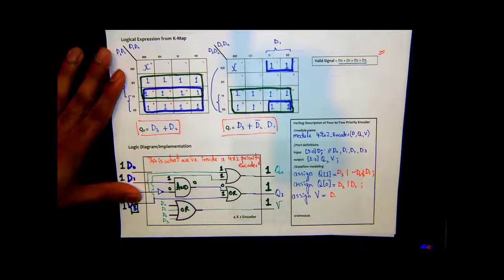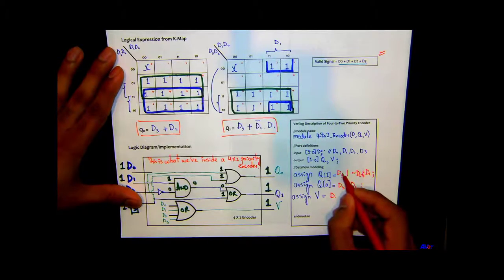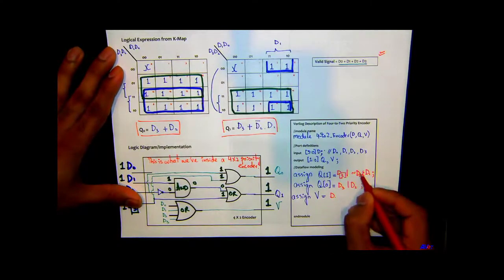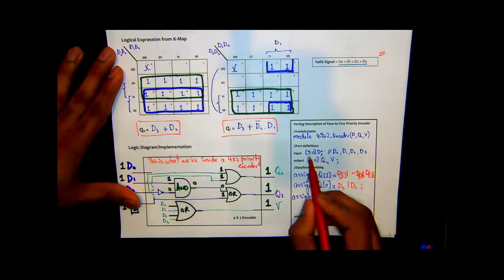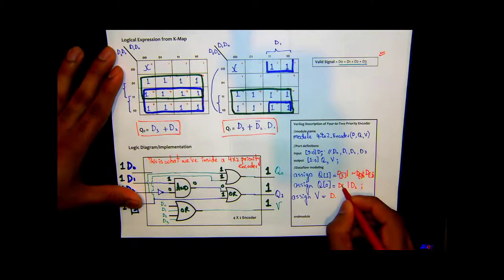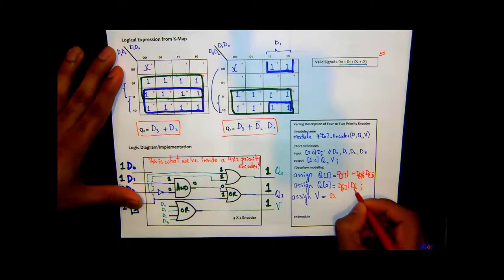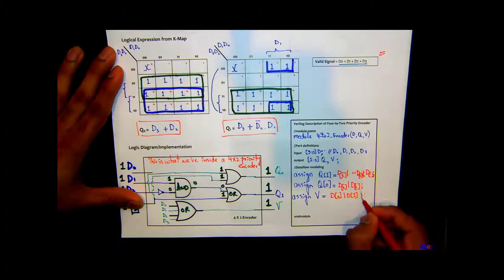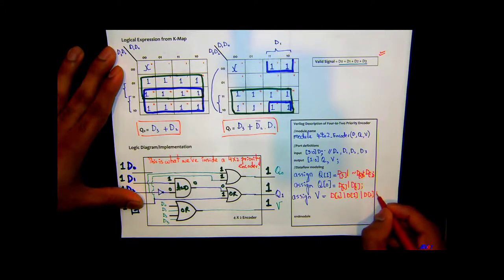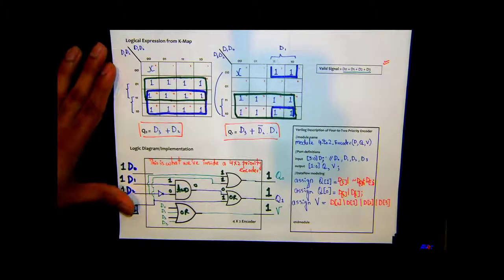One thing that you should remember is that you should always have these square brackets here on the numbers 2, because you have declared them as an array over here. So similarly, you will have D, square brackets, and 3 in there, and similarly over here, D0 ORing with D1, ORing with D2, ORing with D3, and then in the end you say end module.